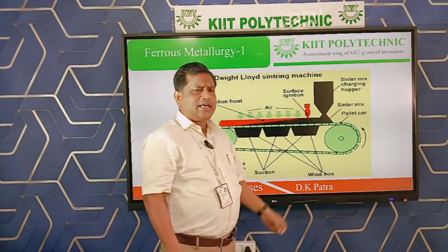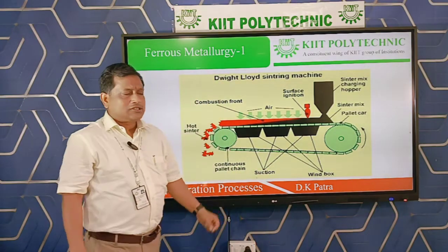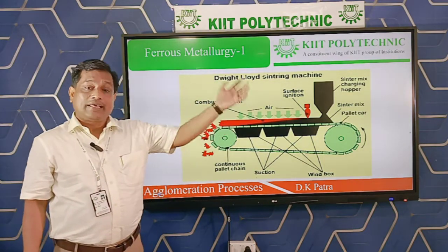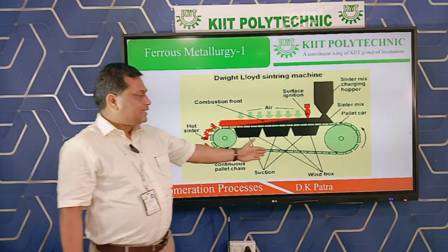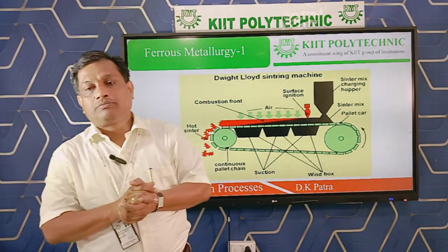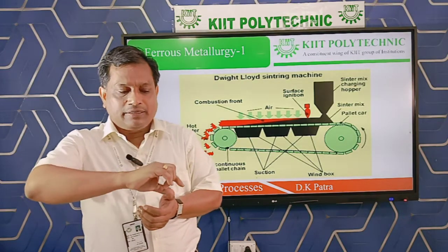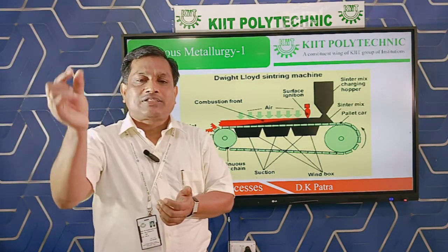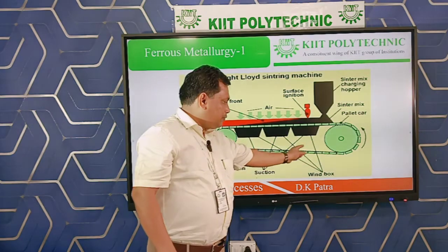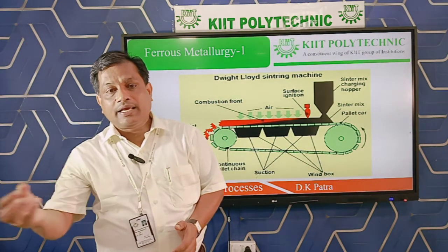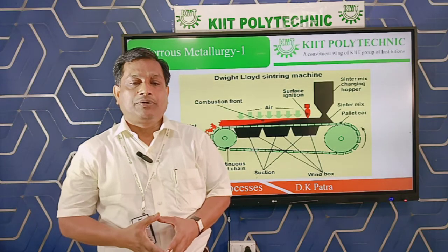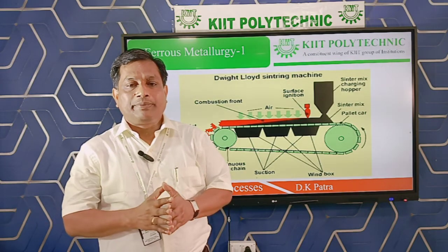Along with the air, small dust particles or small particles of the iron ore can enter. So there is a chance that the turbo blower may choke. So there is a provision that we change the direction of this outgoing air, so that the dust particles will settle and free air will pass through the turbo blower, so that the process can be continued.